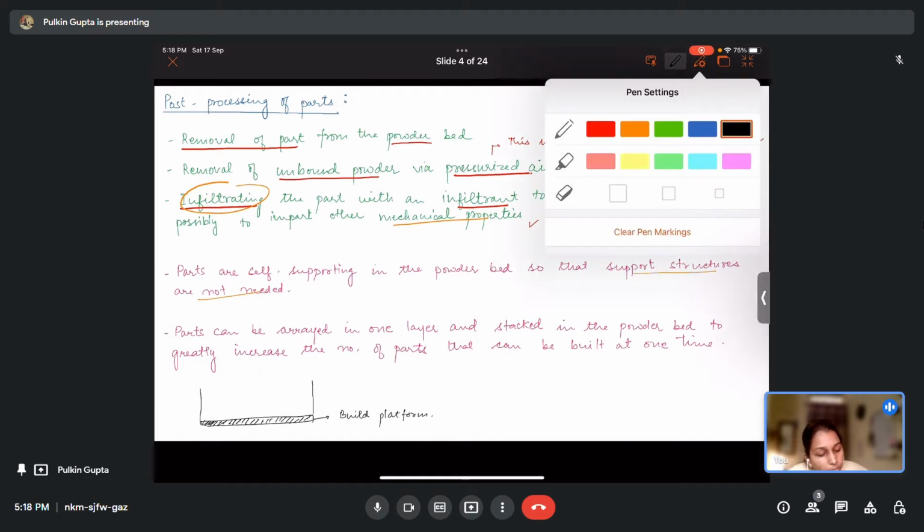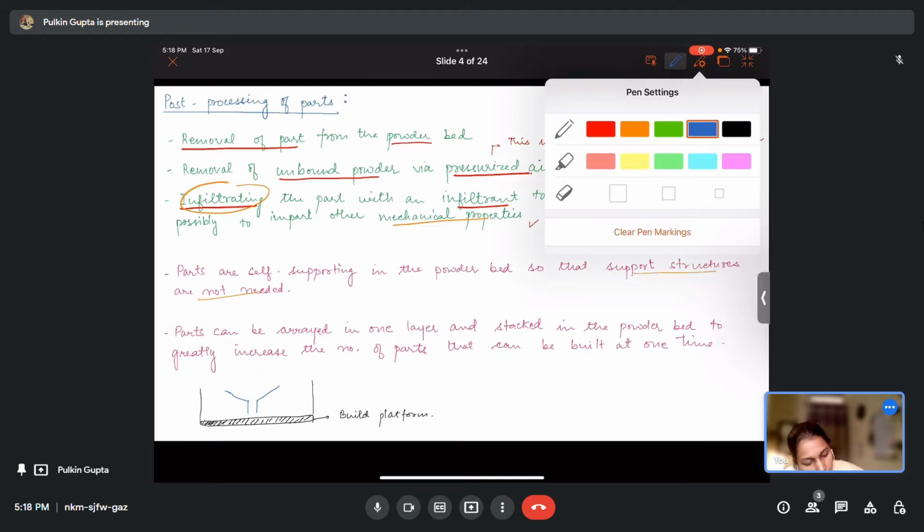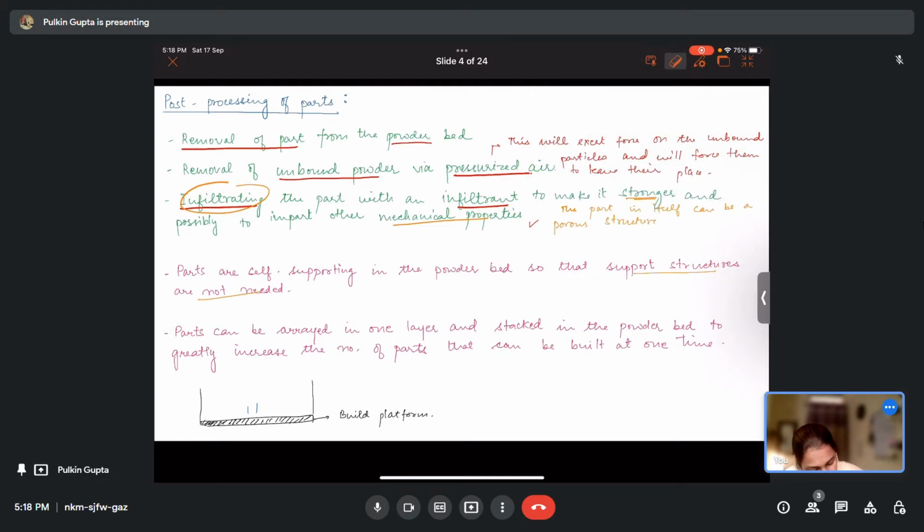Okay. Now you have some part which is having some overhangs. So maybe some kind of geometry, or maybe a T kind of a shape only. So this is the geometry that you are having and you want to print this part. Now when the material is printed here, it doesn't have any support from the base. It's just an overhanging part. So this is your overhanging part, and this overhanging part needs support.